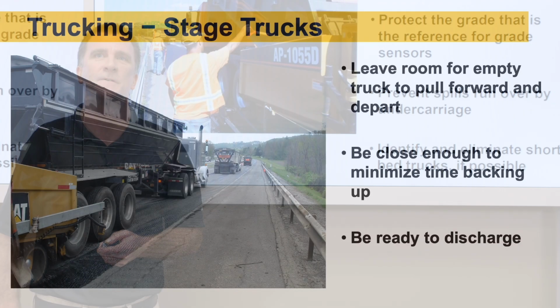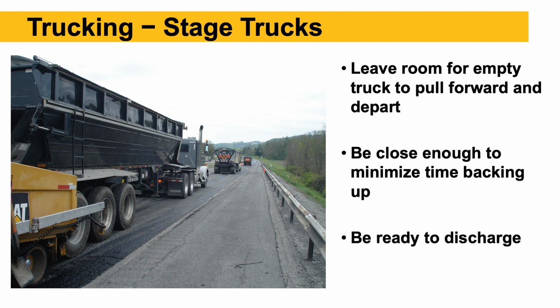Another big thing with mixed delivery on trucks is staging those trucks. So in this picture you can see one truck. This is a live bottom, but you can see that truck is delivering mix into the hopper right now. And if you look ahead, you can see two more trucks at least ahead of that are staged and ready to back up to that paver once this truck is empty and leaves the job. So getting those trucks staged, again, all goes back to training, but we want to minimize any delays. We want to try and keep that paver moving as much as possible.